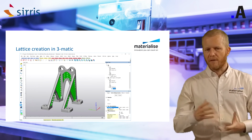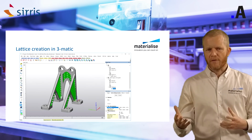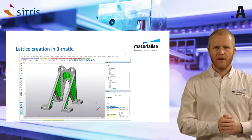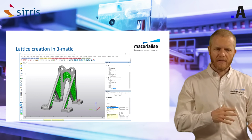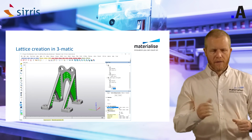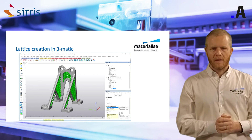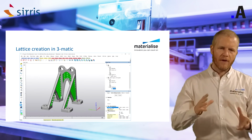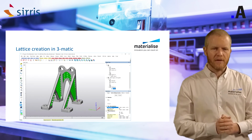Now that the lattice structure has been defined, the next step is to apply the thickness to the beams. This can be done in various ways. You can have a uniform thickness. You can specify a certain porosity that you want to attain, and the thickness will be varied accordingly by the software. You can also do FEA analysis and change the thickness of the beams based on the results of this analysis. Or you can also, as we will see in the next application example, use some image-based thickness for the lattice. Here again, it's a black and white image, and based on the black and white areas of the image, you can change the thickness of the lattice structures.